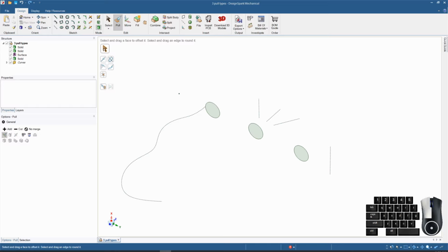And it's a one-time shot deal. So if I select a surface and then want to change the direction of the pull, once I click on it, it's now set there, and if I click on something else, it's actually selecting it to pull. So you have to go back and re-click on the set direction to pull to change it, and it's a one-time selection.